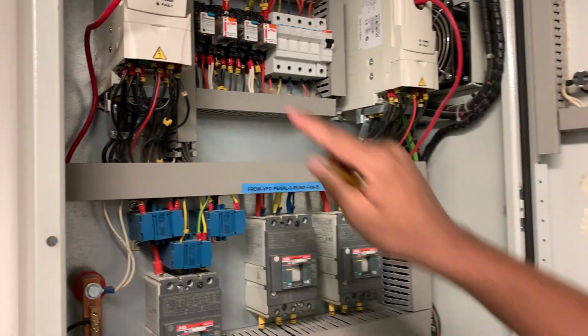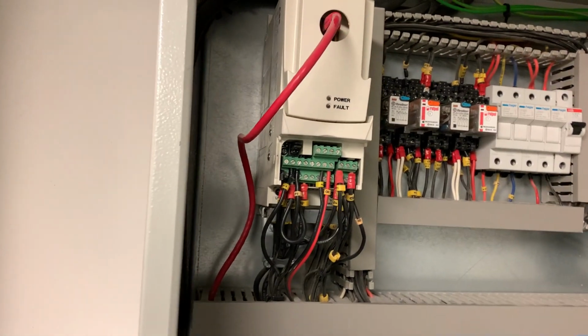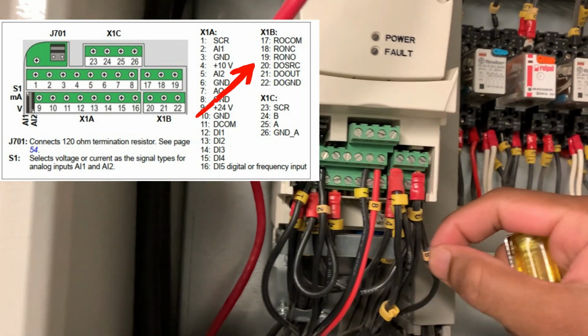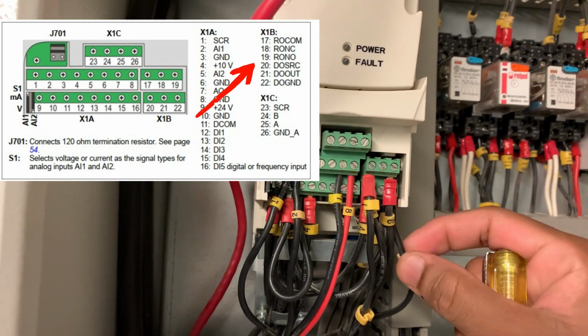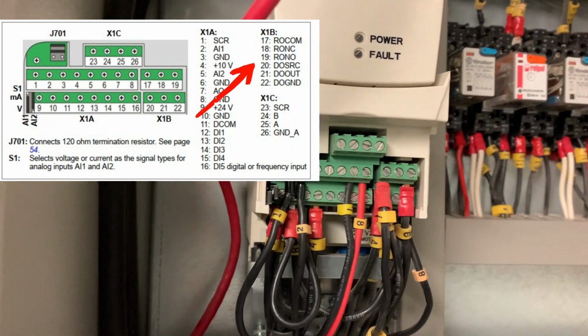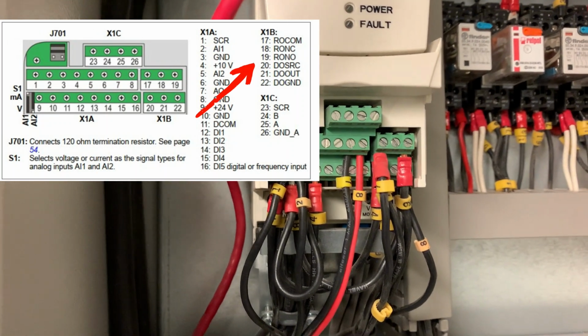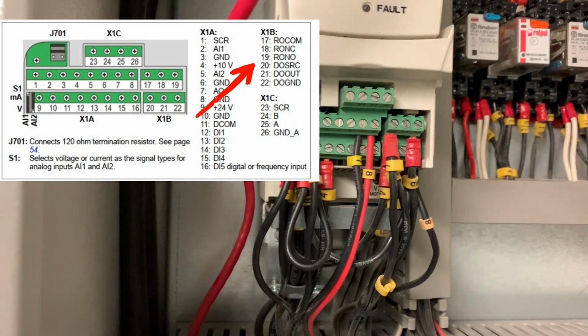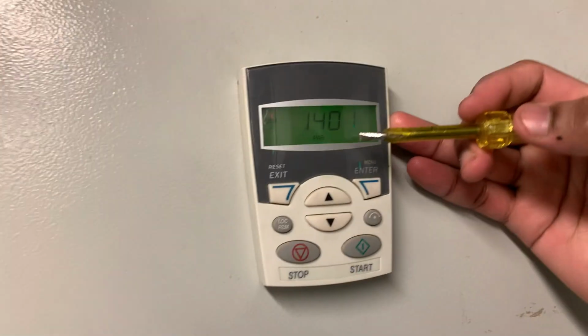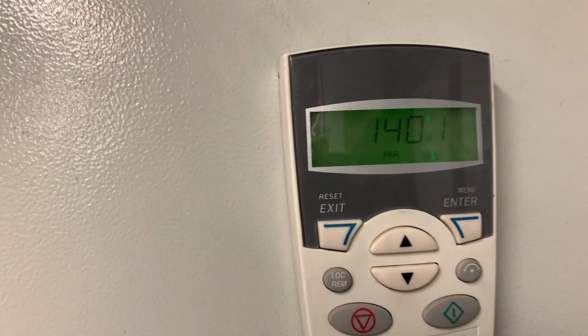As you can see here in the ACS drive, there is one relay, that is 17, 18, 19, and there is one transistor output, digital output. We can use that one as a transistor output, or we can use it as a pulse frequency also. So in the ACS310 drive we have one relay. If you want to configure the relay, you have to go to parameter 14. So let me explain parameter 14 also.